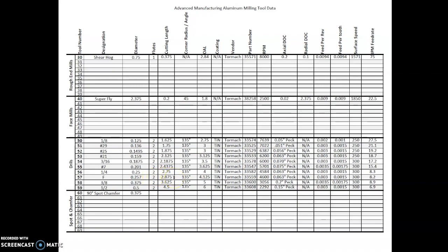Its cutting length is 2.875. The tip angle is 135 degrees. The total length of the whole tool is 4.18. It actually has a coating of titanium nitride, which is a specially heat dissipating material, and also it helps keep the tool lubricated as it's drilling.